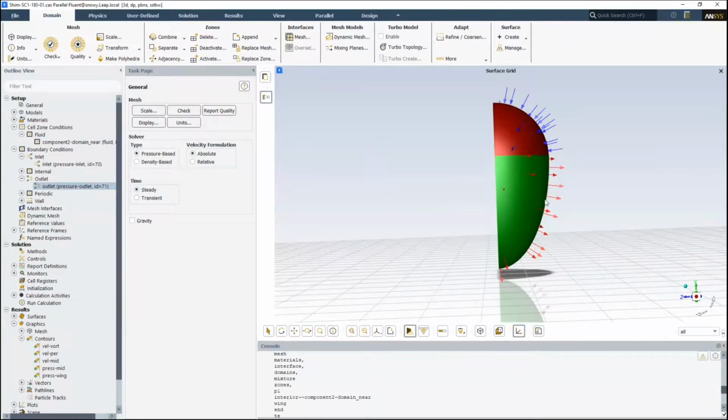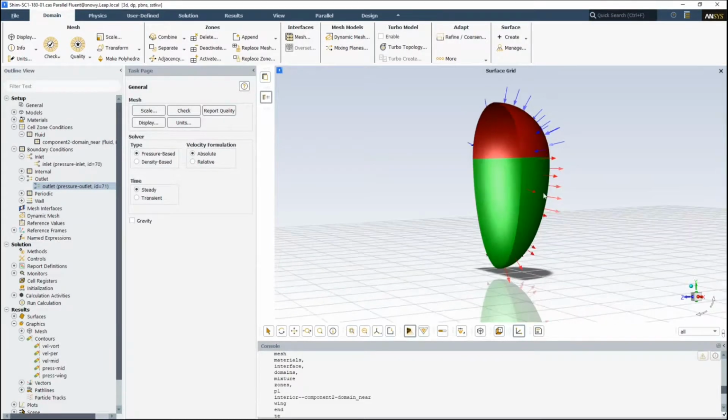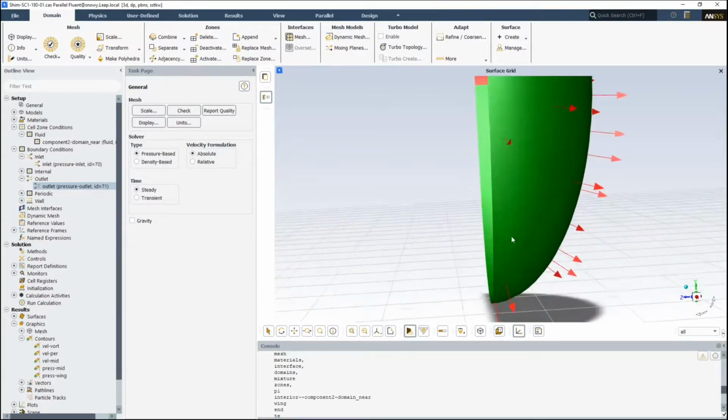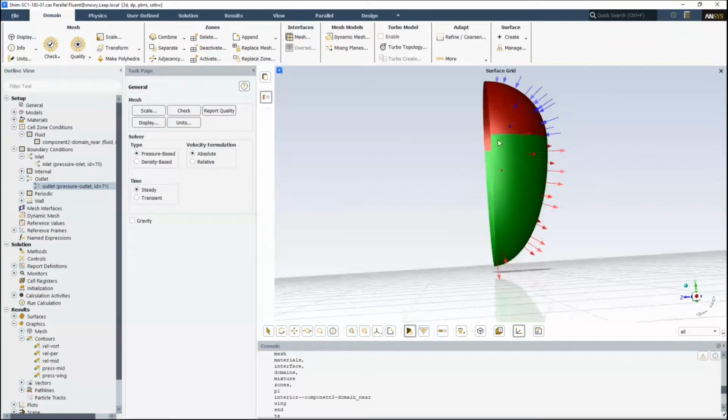And the shape of this is because we want to be able to resolve the flow field for the length of where we expected to see kind of disturbed flow. But we want to have as few reverse flow sections as possible. So what will happen generally is you'll have flow coming down, being forced down by the spinning propeller, and it gets a little bit more chaotic out here, and you'll have some going out and some coming in, right?